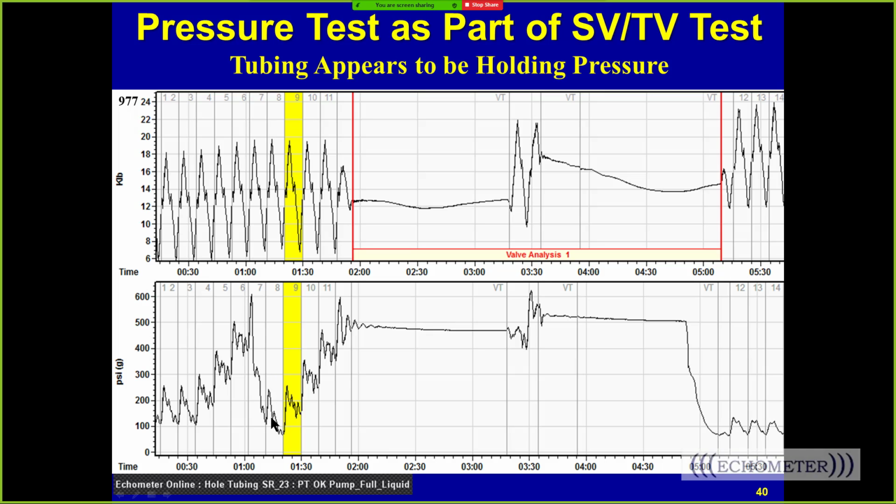We release the pressure, okay, and we're pumping, and then we close the valve, and we walk toward the back of the unit, and we count the strokes. When the strokes get to number 4, we stop, and we hold the pressure, and then we turn for 1 stroke, and then we wait, and then we check and see the pressure's being held, and we leave the pressure off, and this test shows us that there's no hole in the tubing.